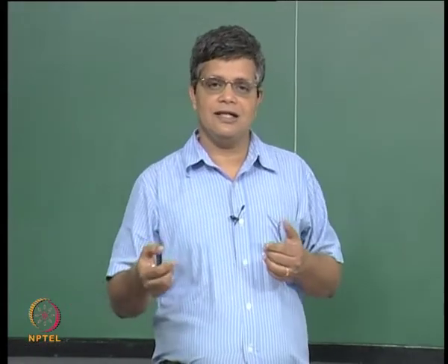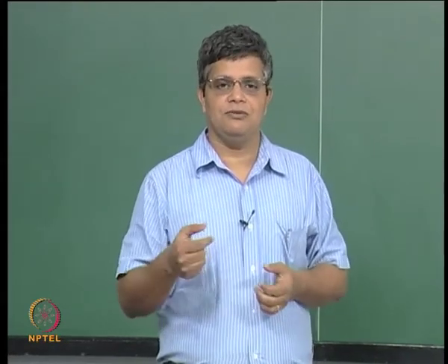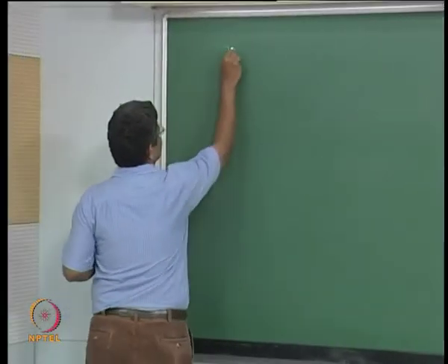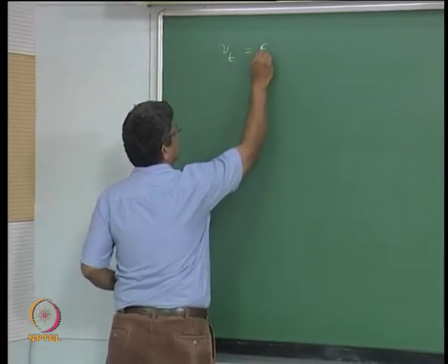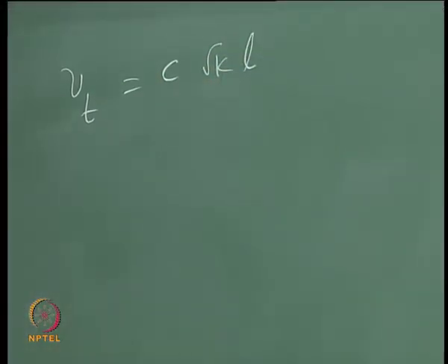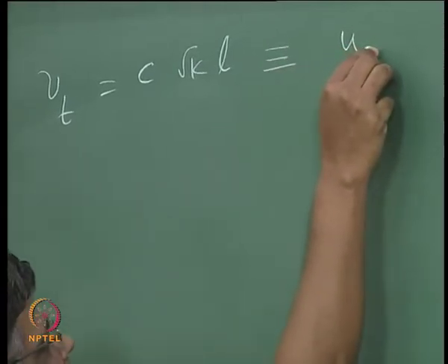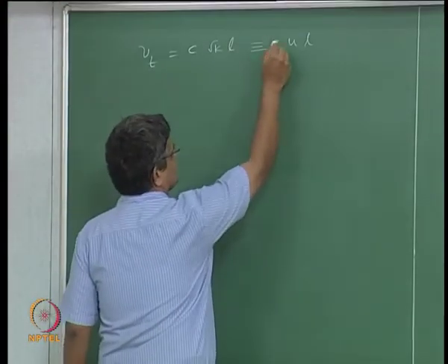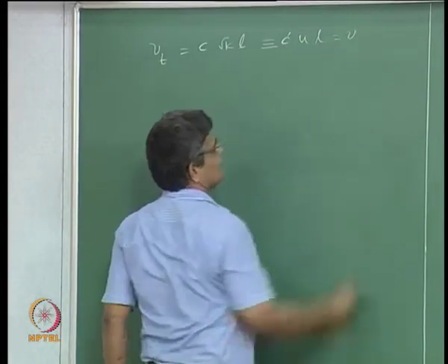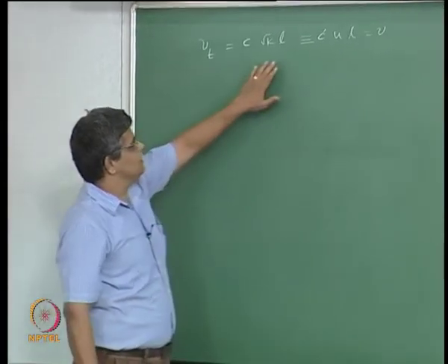So the idea is to derive a length scale which is independent of the geometry, and if we were to have that, then we could write an expression for the turbulent viscosity as being proportional to a constant times the square root of k times the length scale, which is analogous to u times L times a constant c prime, which is characteristic of the molecular viscosity as per the kinetic theory of gases. Now, what can be the length scale here?